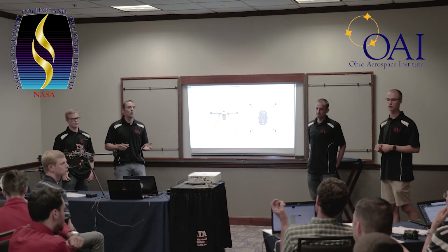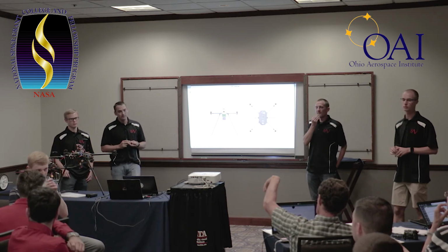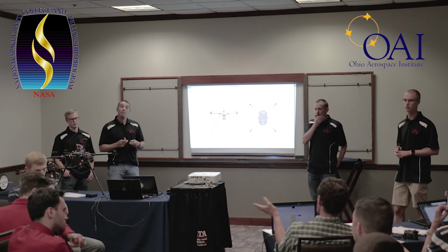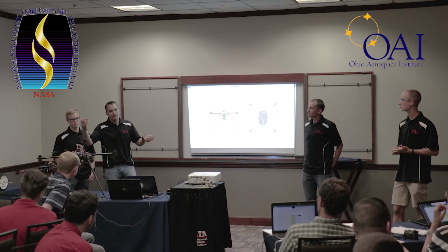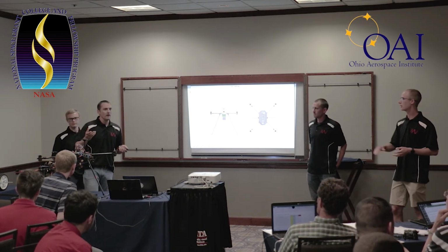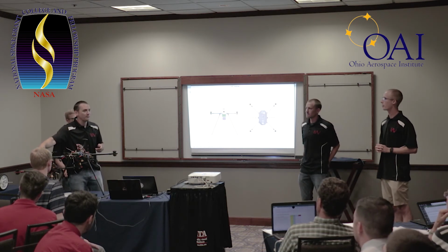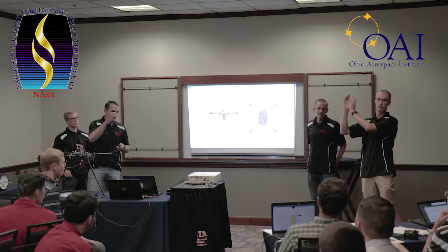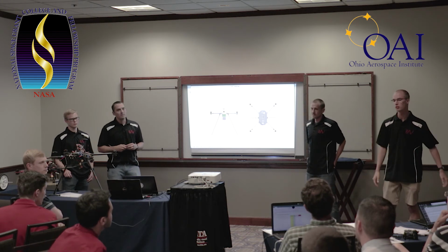So the one below is undersized, smaller than the one on top, even though now it doesn't have a downwash to compete against it. It's still powered less, and the Pixhawk is going to offset for that. It's going to recognize that, and again, there's no encoder, so it's not talking back. It's not saying, hey, I'm not spinning at the right rate. Pixhawk just knows that there's not enough thrust coming from this corner arm, and it increases the signal on both of those arrays.